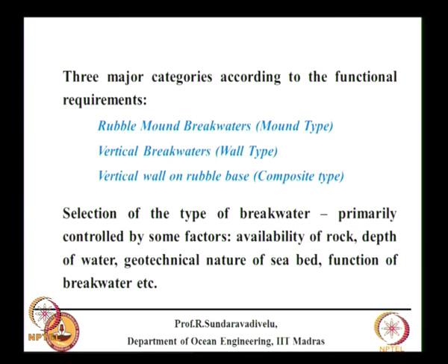Another thing is there are certain conditions for this rock, it is not that all the rocks can be used for breakwater construction. So the rock that can be used for construction, if it is available, let us say within 30 kilometers, then we can go in for rubble mound type. 60 kilometers also is possible, at more than 100 kilometers we should think of some alternatives.